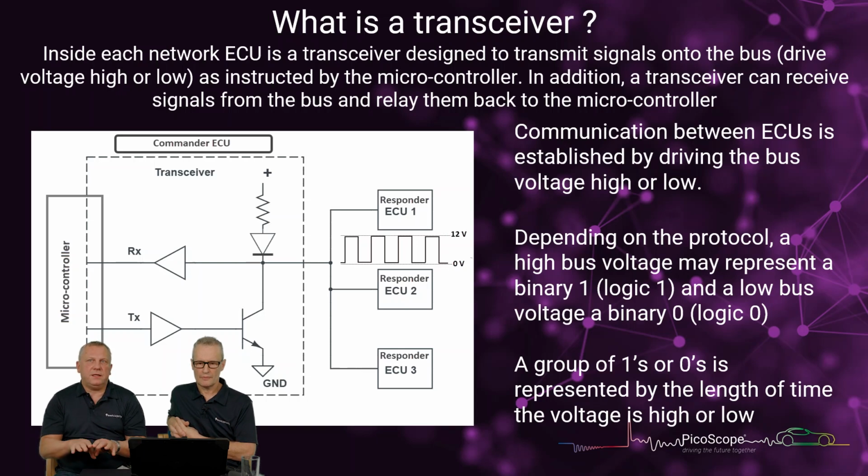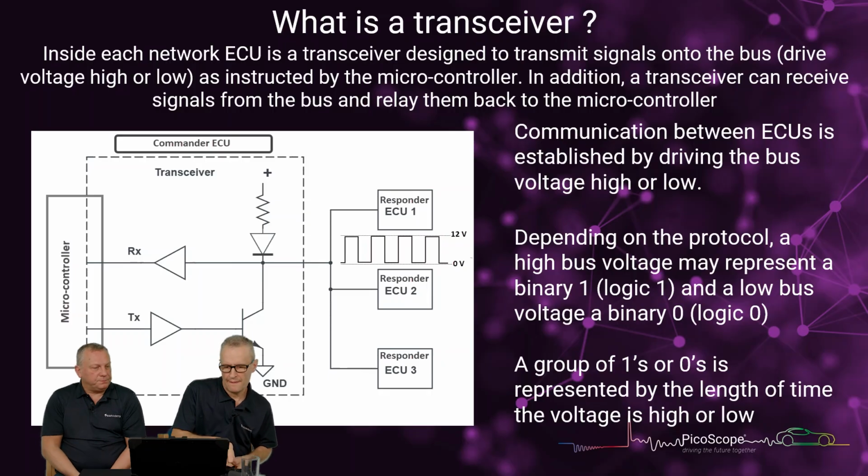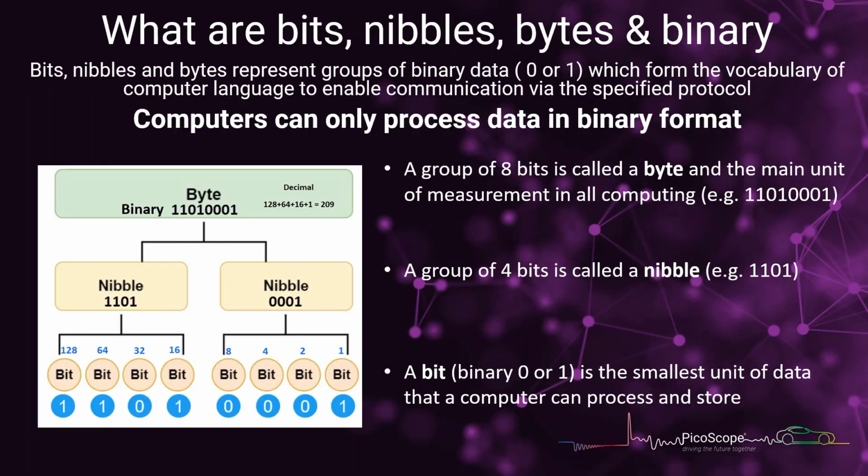So it's exactly the same as doing a volt drop test on any particular component. It's just that we're going to be measuring after the load. Until the load is grounded, which is the pull-up resistor, you will have 12 volts if it's configured this way. And when it's grounded, it goes down to the lower voltage. Yeah, thank you.